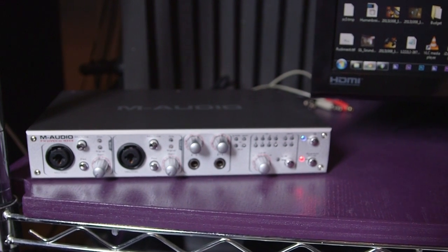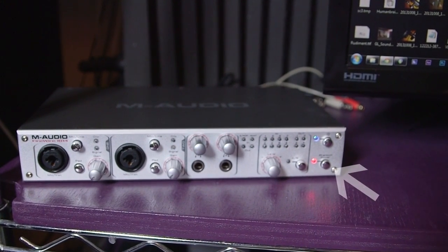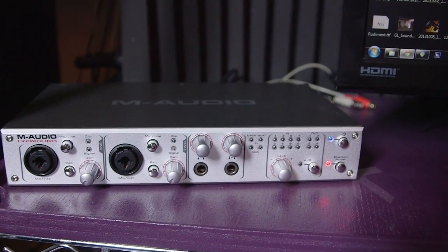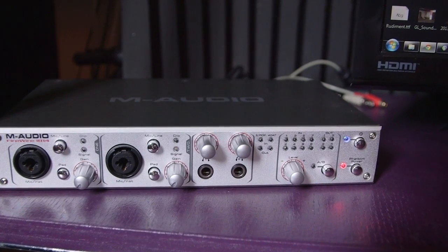If you are using a condenser microphone, make sure phantom power is turned on. You may also want to look at the documents of your interface or preamp to see if there is any specific instructions for turning on phantom power. Some nicer preamps ramp up the voltage on the phantom power, which can be a little more gentle on the electronics in a condenser microphone. I have never had a problem plugging in a condenser mic and then hitting the juice, but it might be worth checking that out.